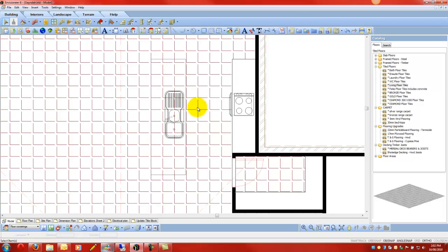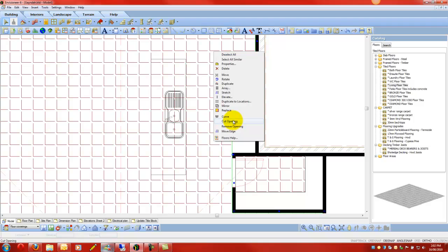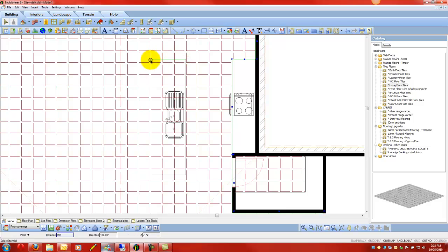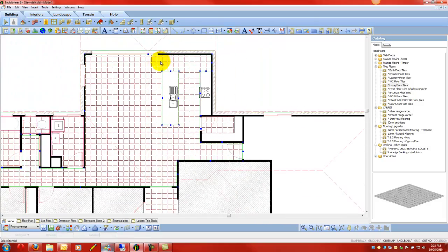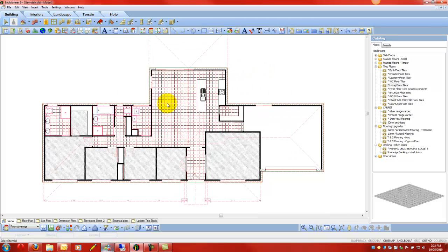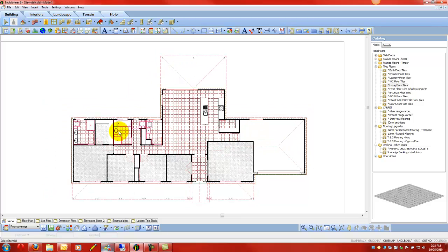Now this one is inside of construction lines, but if a construction line is put in the centre of a room like this, for some reason it's broken. The thatching still goes under it. So in this case we need to select the flooring, cut opening, oops, cancel, cut opening, and go around the house like this, finish. Now what we've done, if you look at the plan now, it looks a lot smarter. You can see all the different areas inside the house, because we've cut the floors around, so you can understand that we haven't lost anything.